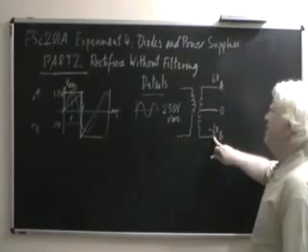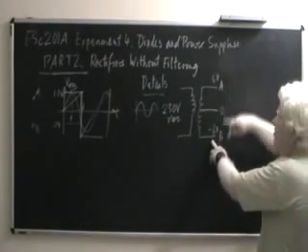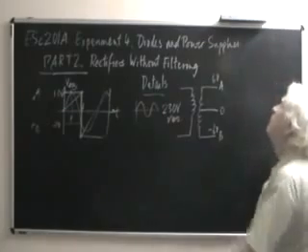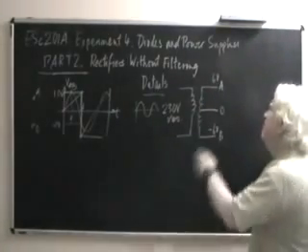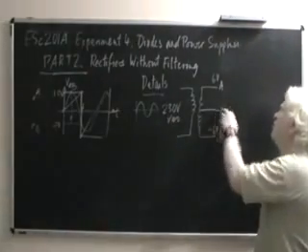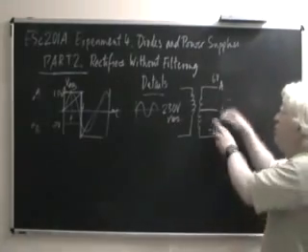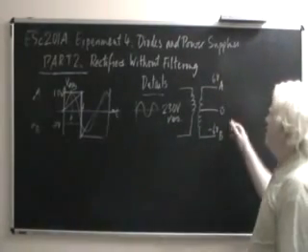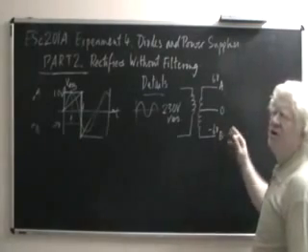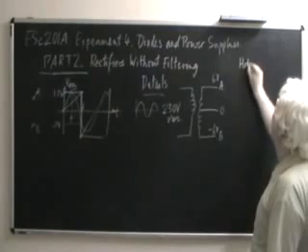If you make this the reference, then A will have plus 12 volts with respect to B. If you make A the reference, then B will have minus 12 volts with respect to A and minus 6 volts with respect to this O point. So you can use this in various ways, and we now use it in two distinctive ways. One is to build a half-wave rectifier.